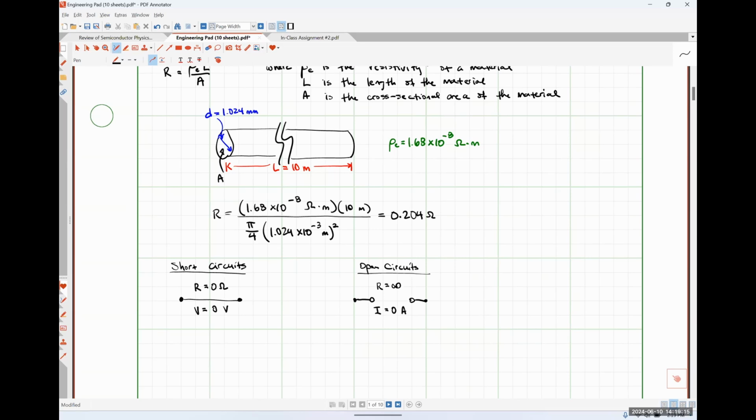With regards to an open circuit, well, really, it's just got a very, very large resistance. It isn't infinitely large, right? Some of you have probably seen sparks and stuff like that come out of outlets when you plug things in or unplug things. And that's because if the potential difference is high enough or the voltage is high enough, we can make current flow through air, okay? It depends on what's called the dielectric breakdown voltage of the medium.